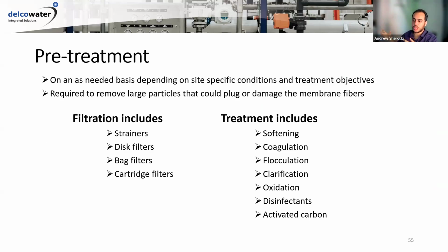And this is in the cases where you have really challenging water. However, the UF can handle up to about 100 or 150 NTU. If you have even dirtier water than that, you might need something like a big strainer or disc filters or conventional treatment before the UF, so that you're not plugging it up too much and you're reducing the hassle of the cleaning cycles. Obviously, that comes with a greater cost, so it becomes a balance of operator ease versus capital cost.